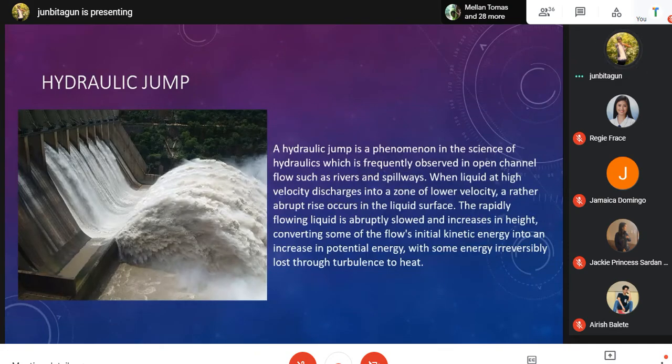To convert the energy because of it slowing down, remember you did the Bernoulli equation on a certain streamline, the energy there should be equal. What if you suddenly increase the height at that particular point of the streamline so that the energy between the 2 points is equal? Since they are of the same streamline, something will adjust. We have three in the Bernoulli equation: velocity, pressure, and height. So here, under hydraulic jump, it would be the energy due to height that adjusts. That's why the water rises when that happens.